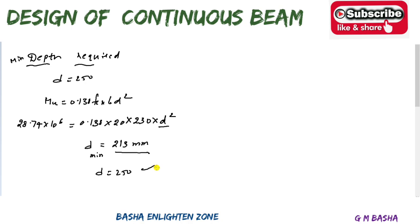For example, if you prefer D to be around 150 or 200 mm, definitely we have to change this, as D minimum is restricted to 213 mm. At that time we have to provide approximately 220 mm, and we have to redesign this one. Here we are already on the safe side only.